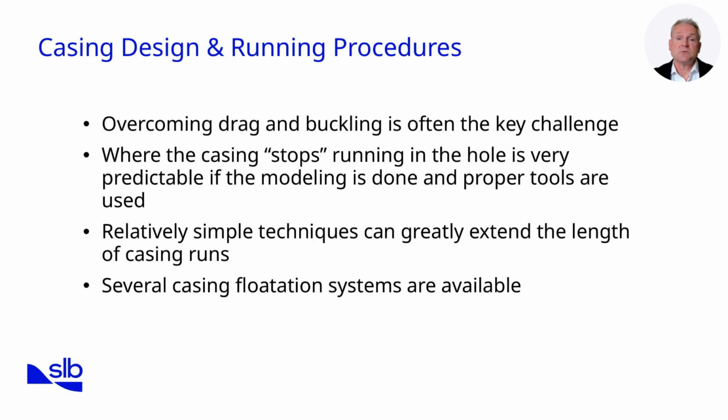In extended reach wells, casing design and running procedures often become the critical bottleneck. The main challenge is overcoming drag and buckling. With long departure lengths and shallow true vertical depth, the casing experiences much higher axial and lateral forces compared to conventional wells. One key point is that where casing stops in the hole is actually quite predictable, provided the right modelling and tools are used.